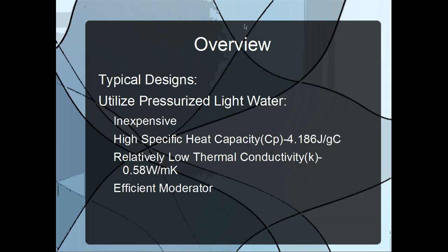Under steady-state conditions, liquid water has a low ability to conduct heat. The thermal conductivity of liquid water is low at 0.58, when compared to the high value of liquid sodium at 86. Liquid sodium is used in some fast breeder reactor designs and as a thermal storage medium in many solar plants for its heat capacity and thermal conducting characteristics. However, liquid sodium does not work well as a moderator, which is the third reason water is used for this